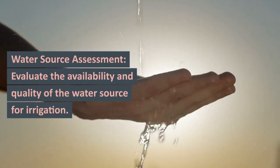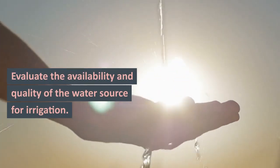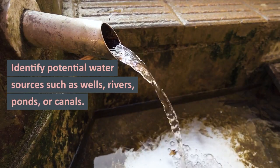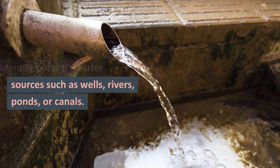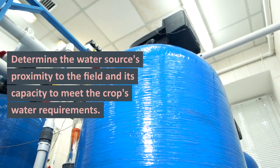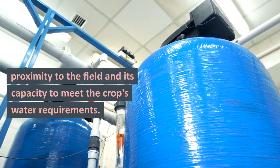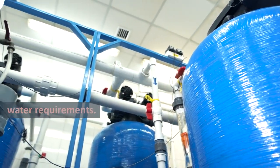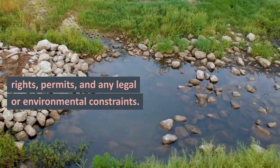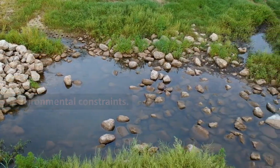Water source assessment. Evaluate the availability and quality of the water source for irrigation. Identify potential water sources such as wells, rivers, ponds, or canals. Determine the water source's proximity to the field and its capacity to meet the crop's water requirements. Consider factors like water rights, permits, and any legal or environmental constraints.